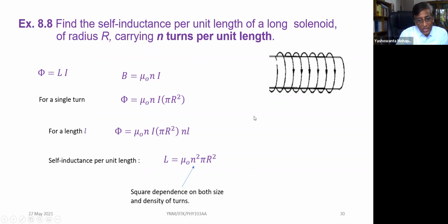If you want to change the current, then the size matters. If you change N, you could get more magnetic field, but then changing the current becomes harder by a square. You could link more flux, or make the size of the solenoid larger, but you would be paying in terms of inductance, by a square. That's important. It's a simple derivation, but a very important formula on the practical workbench. So this is important in design constraints.